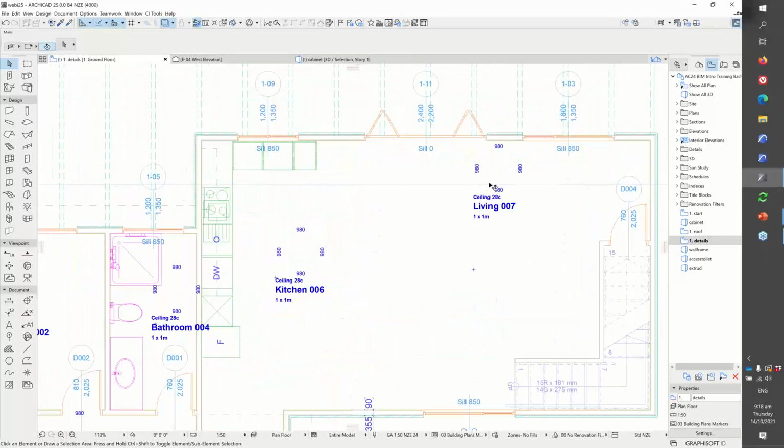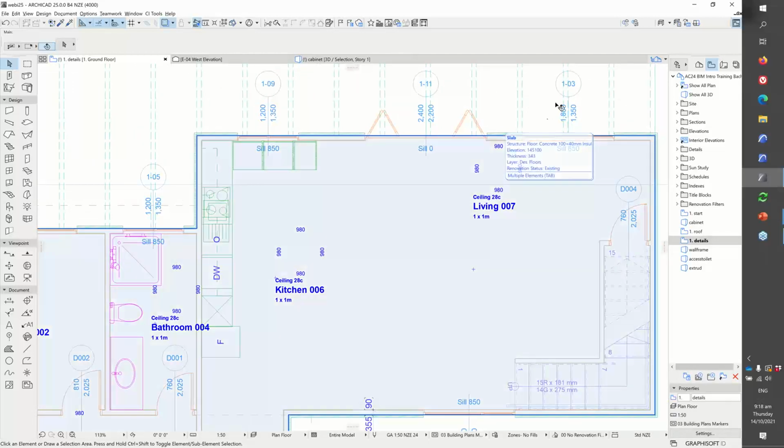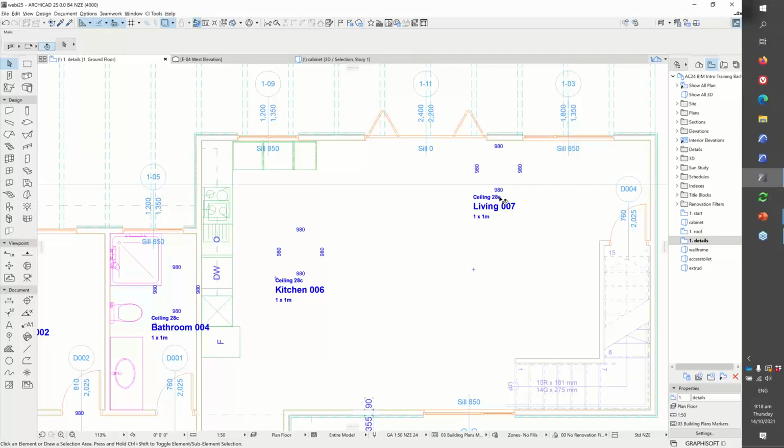And you can see if you've already been using this object, it's been around for, I think, a year or two already. And normally what you need to do with it is that once you place your zone, you have to resize the stamp to fit the size of your room, and then it will give you nice dimensions around each of the sides of the zone, and then give you a rounded measurement below the zone stamp.